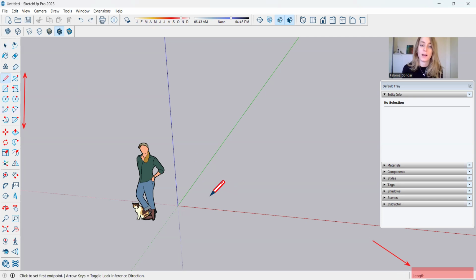So I'm gonna start with one left click of the mouse. And while I'm moving, we're gonna see that now it's red and it says on red axis, black, then green on green axis, and blue on blue axis. Those three colors we need to focus on while we are drawing. Another thing here, it says length, and while I'm moving the mouse, the length changes.